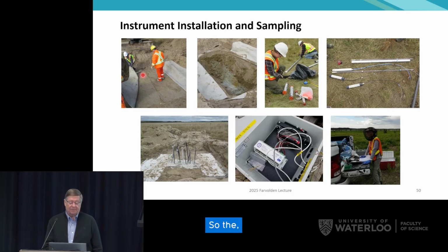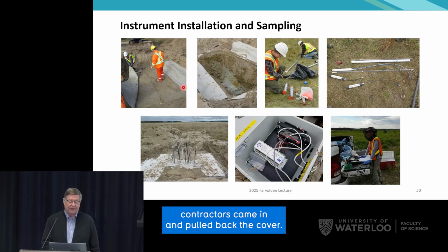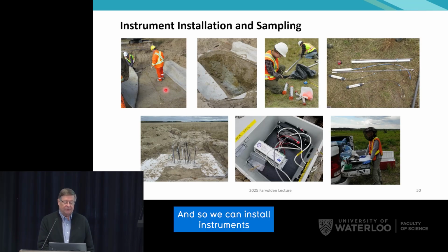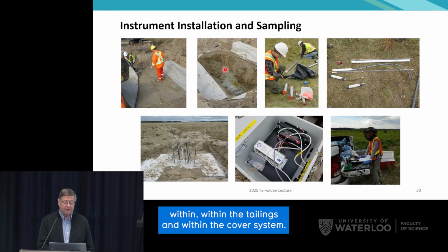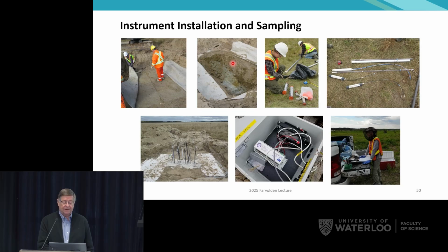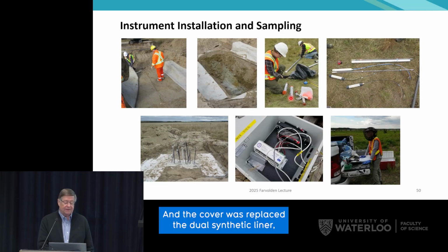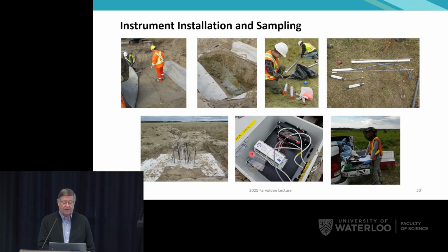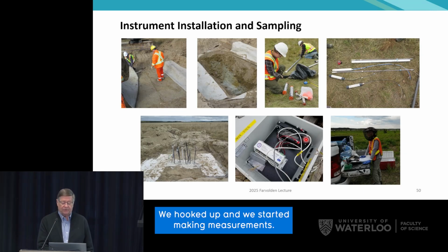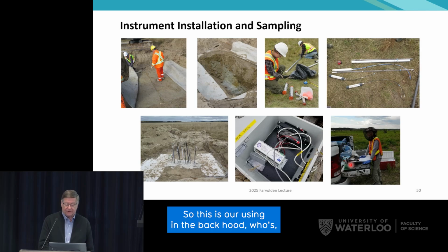So the contractors came and pulled back the cover, and so we could install instruments within the tailings and within the cover system. And we collected cores and installed a variety of different instrumentation. Then the cover was replaced. The geosynthetic clay liner was reinstalled. Data loggers were hooked up, and we started making measurements. So this is Arya Zhang in the bug hood, who did her master's thesis on this project.